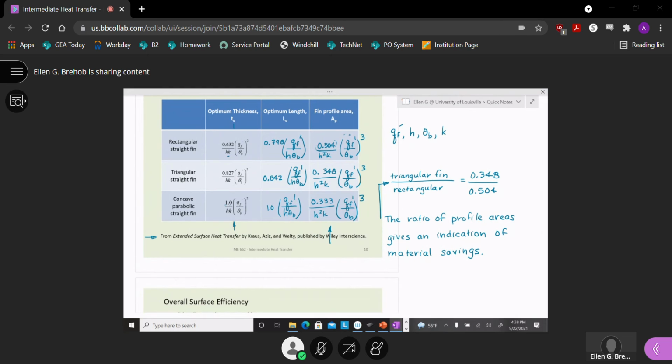And then likewise, it says something about if I can drive so that I have a bigger temperature difference, the base temperature of the fin, that we probably can't control, but if I can cool the air off to increase the free stream temperature, that difference is then magnified by a power of 3.